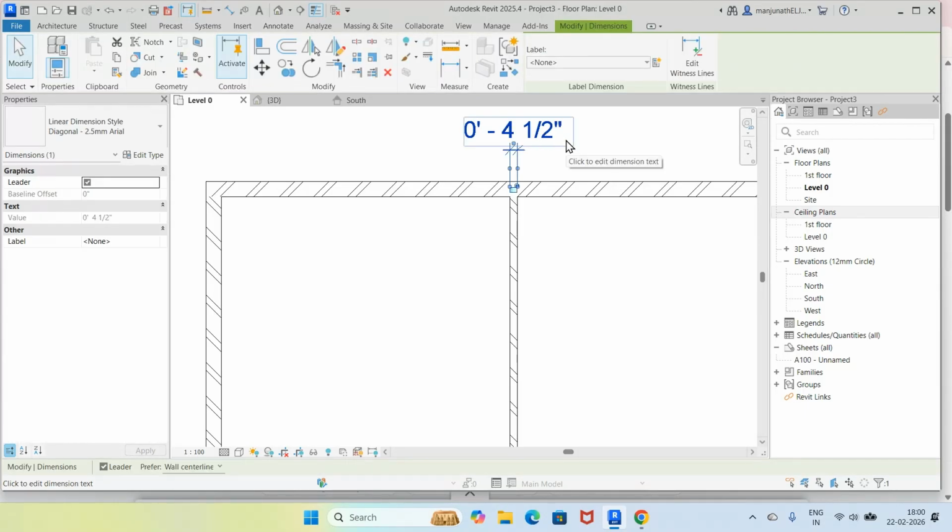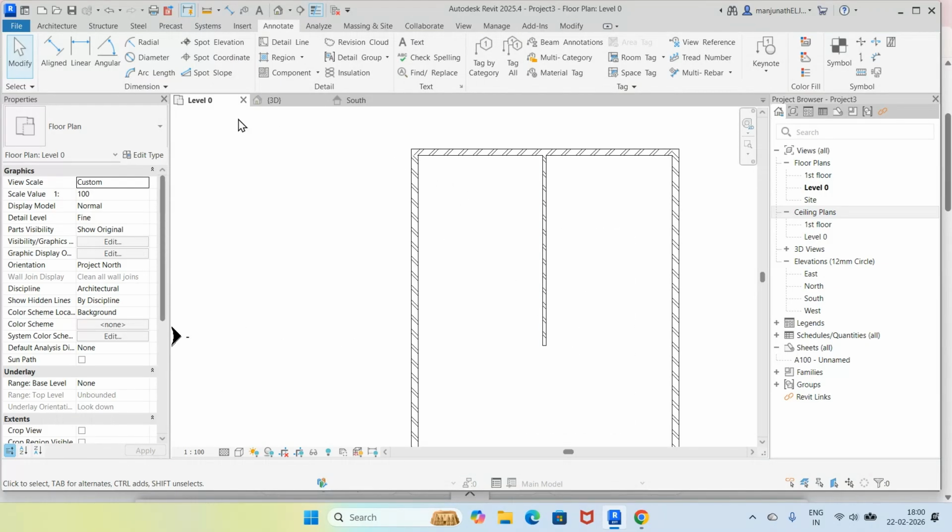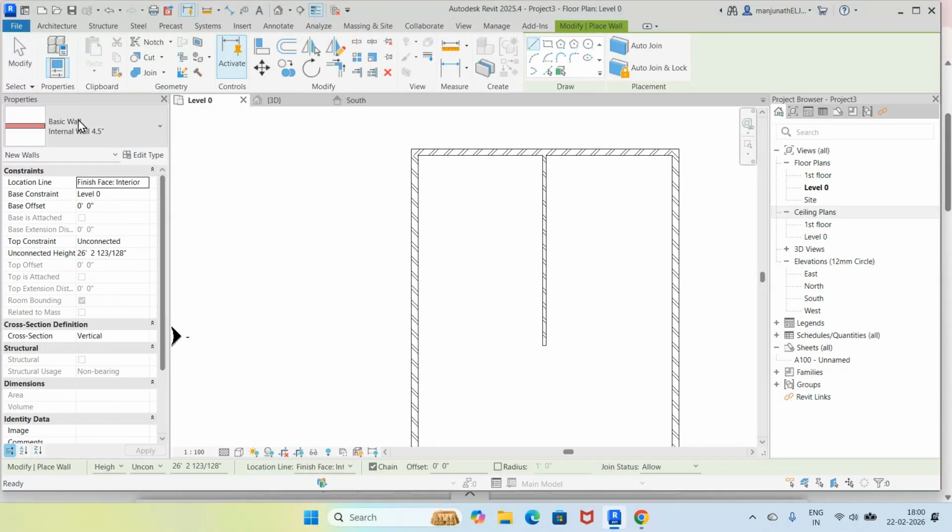Now, similarly, I will just take the internal wall again. I will just go to architecture wall and I take basic wall. Now the location is face internal. So from here, I will take it on this side now. Correspondingly to that wall, you give the dimension. You just go to this and whatever I want, I will say I want 15 feet. I will just take 15 feet. So from here, you have an internal wall, correct? But now it has taken for the external one.